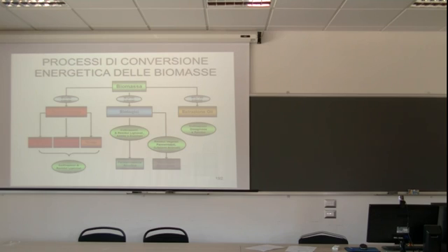316 steel performed very well at 200-300 degrees Celsius in a salt-induced corrosion environment, but as the temperature went higher, it performed badly. But then there was a high chrome nickel steel, an expensive aerospace alloy, that performed really well at high temperatures, but as soon as we dropped the temperature, its performance went bad. There are other issues like mechanical properties, but we were just focusing on that. So that's why I suggested we should try other compositions for the current collector.